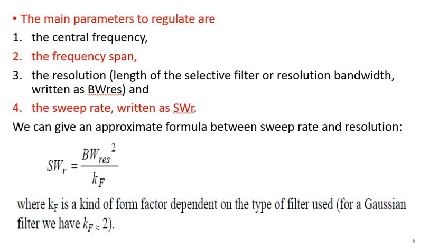And in this case, the resolution is nothing but the length of the selective filter or the bandwidth of that selective filter. What is the lowest frequency it can allow, and what is the maximum frequency it can allow? We can always design our filter to suit our own requirement. And the last parameter we can regulate is the sweep rate.